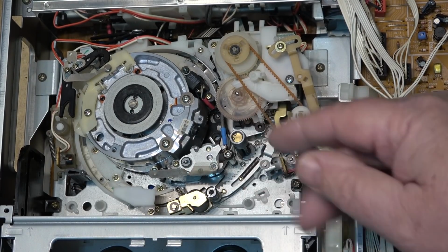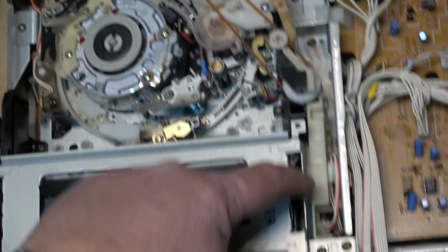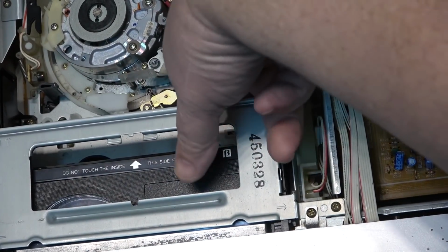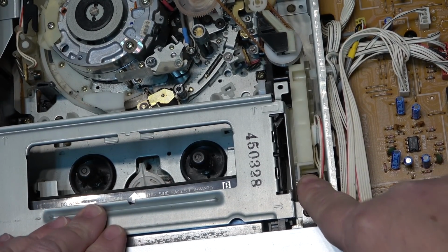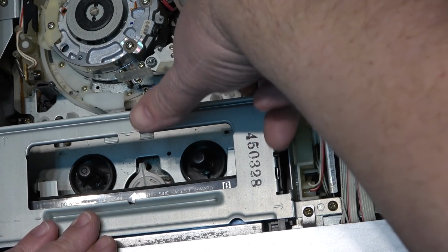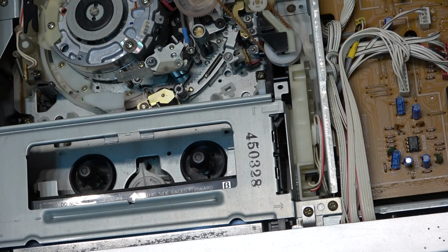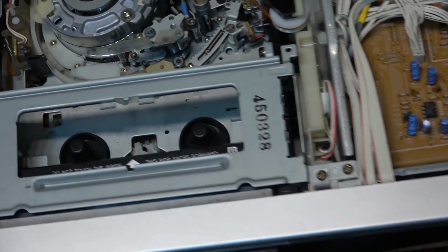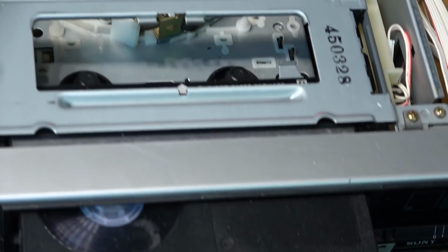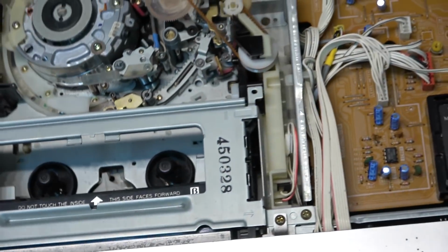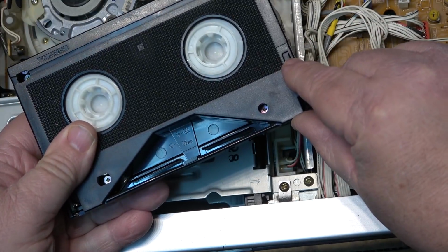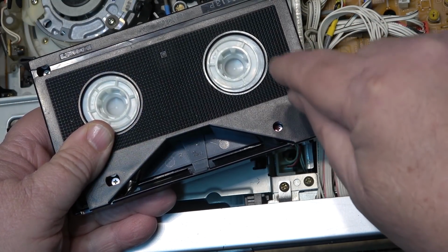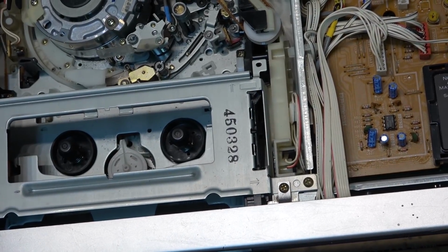Once it loads, it's going to activate a switch over here. Actually, it's underneath here. There's a switch on the back here which tells the system to load, and there's another switch underneath here which gets activated. You can see it if I tip the machine up. See the little pin switches there? One of those pin switches is used to detect if the tab is broken, the record tab. The other pin switch is used to detect that the tape has been dropped.